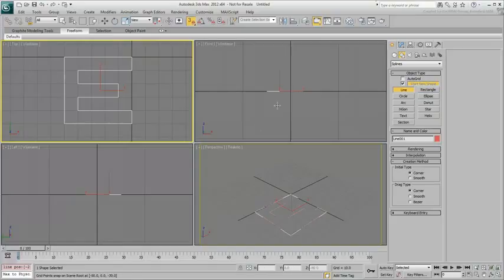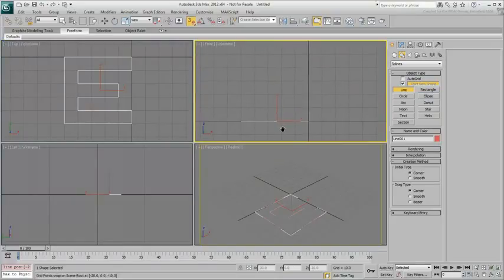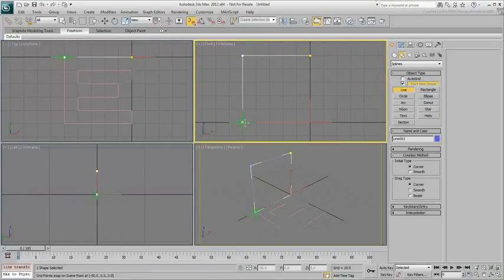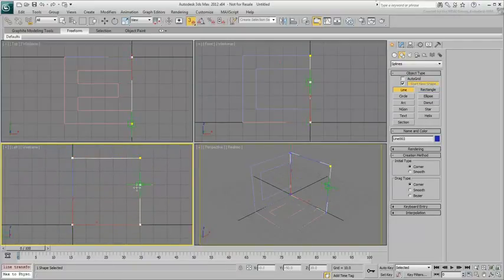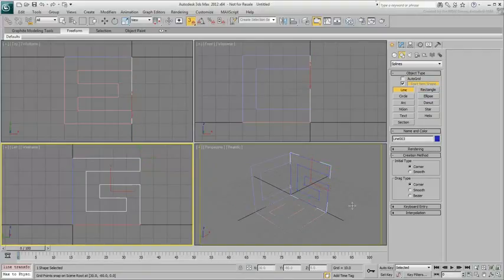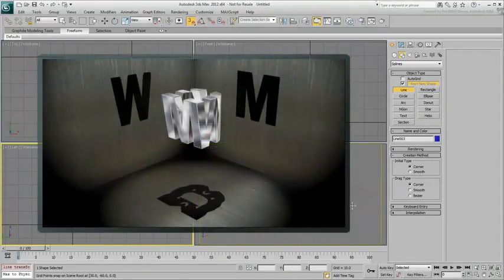In the front view, create the letter C in the grid's top left quadrant. Again, confine yourself to a 5x5 grid. In the left view, create the letter G in the top right quadrant. Theoretically, you could use any letters you want, but be advised that some letters work better than others. Curved and sloped letters would yield artifacts in the shadows.